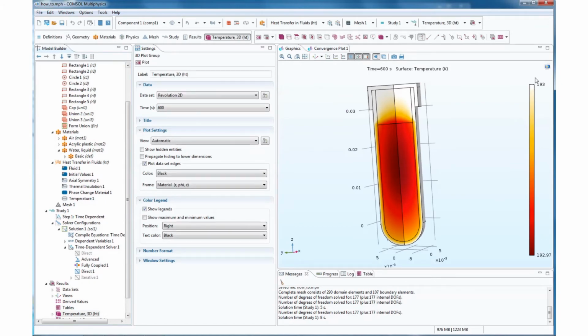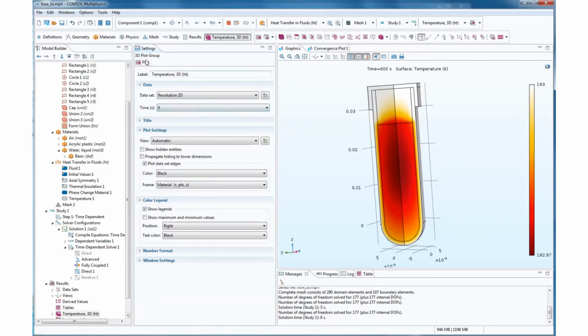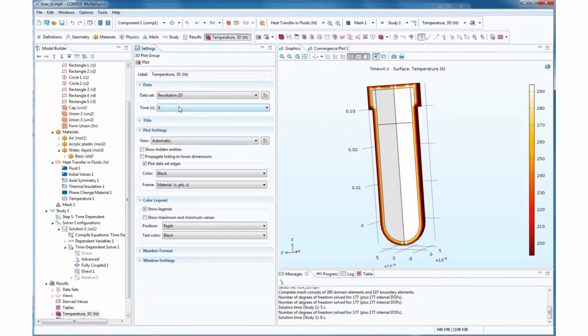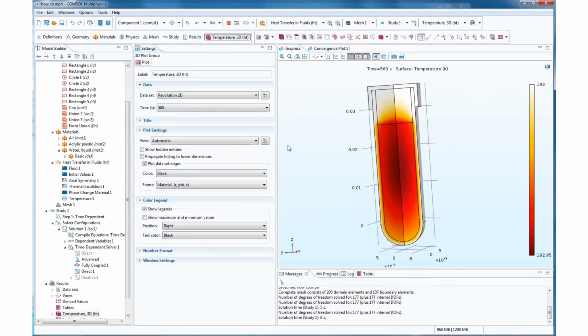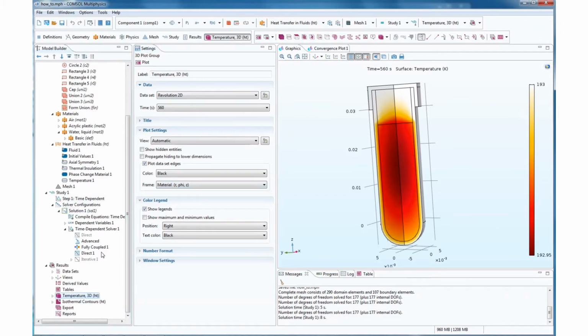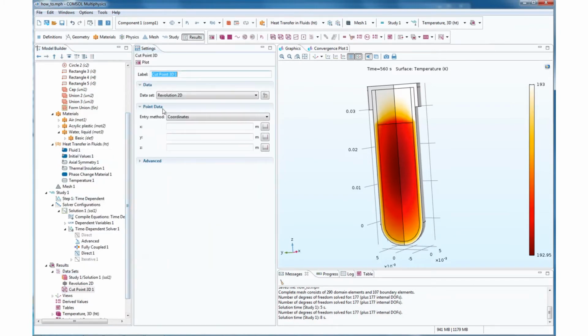The scale is really annoying in COMSOL because it'll just change based on whatever. Here you can see it's 192 to 193, but now it's 200 to 290, which is a much greater change, and the colors are kind of frustrating, but you just make sure you look at the temperatures defined on that color scale.